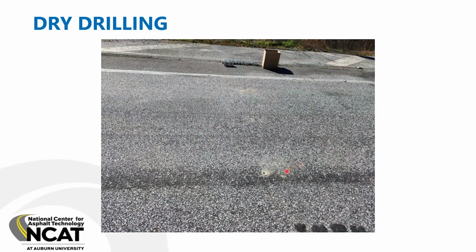And so here's some of these cores. There are little dry auger holes that we've drilled. You can see they're very small. It's a fairly quick process. You can sample a bunch of different holes, and it's invasive. You are drilling a hole in the pavement, but I would call it minimally invasive. But maybe laparoscopic is the way to look at it.